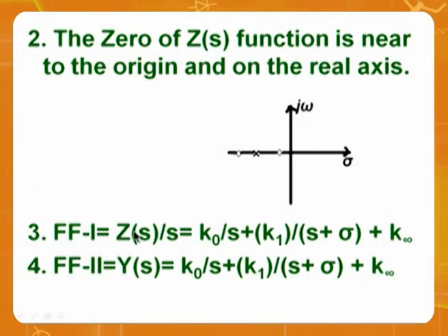To avoid the capacitor, I am dividing by s. Then what happens? The s's will cancel. You will get a resistor there. So wherever there is a possibility of getting a component other than the component that we expected, go for dividing with s. That's a very simple, customary thing to remember. You can easily get it. You don't need to mug up here. You can just try. As you do it, you will understand.